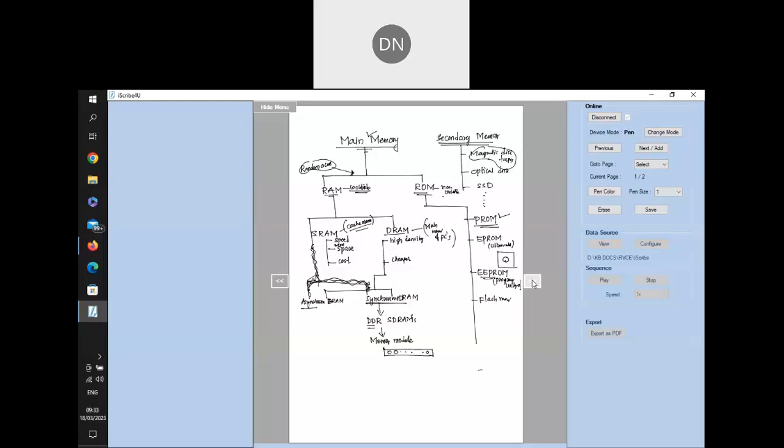But the only disadvantage is that you can read any location randomly, whichever you require, but when you want to write, you have to write the whole page. You cannot write a single word in SD cards or flash memory chips. You cannot just write into one particular byte or word. You have to write the whole page. So first we have to read the page, modify whatever is required in a buffer, then erase the whole page, and then write it. This is the one disadvantage of flash memory.